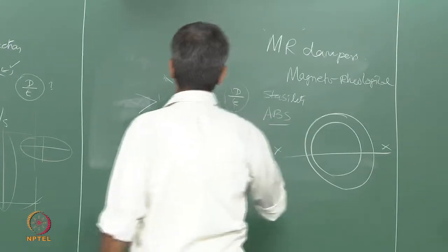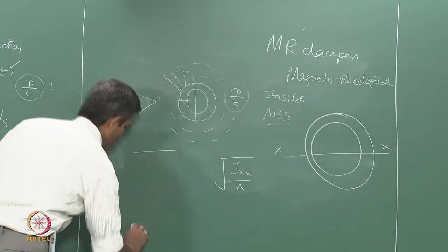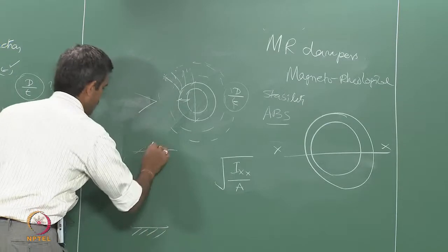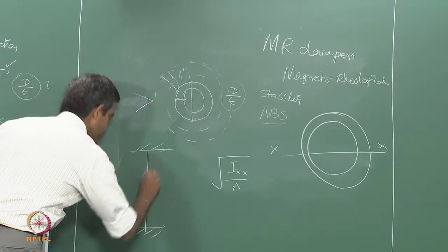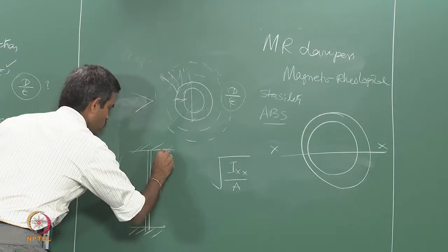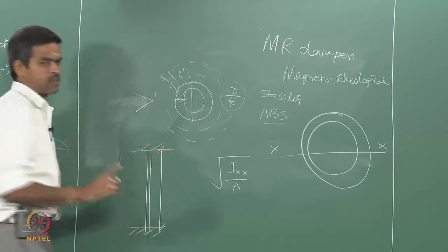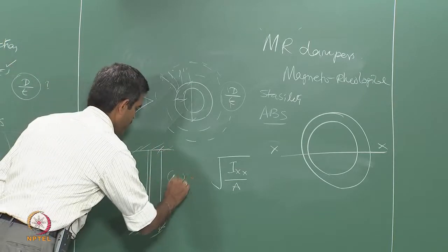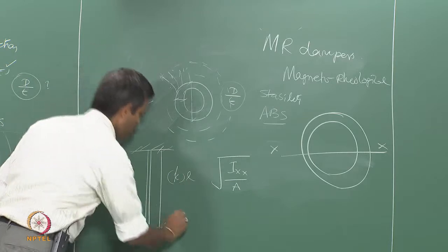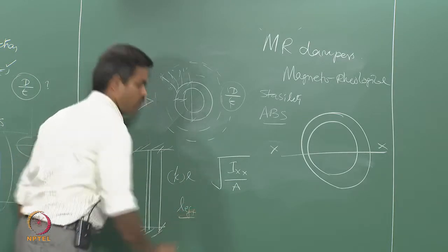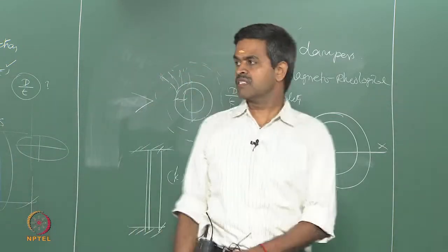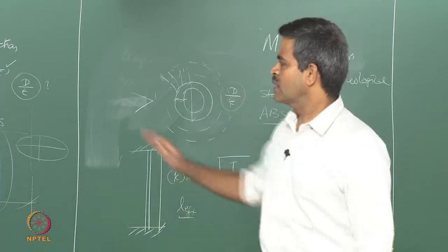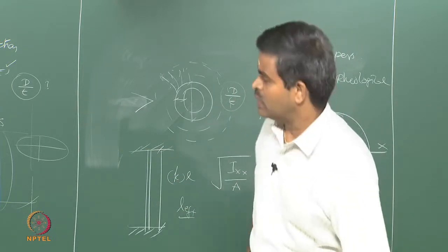And of course, if this member has connections at the top and bottom which are both fixed, let us say, I should be able to compute the unsupported length. Please do not multiply any factor here. Do not try to work out L effective, try only the unsupported length, that is the connection from top to bottom. So, L is an unbraced or unsupported length.